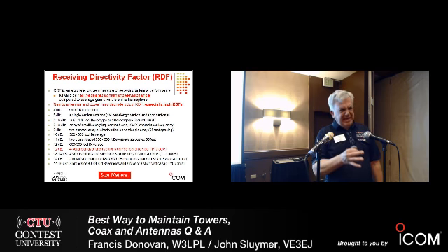Magnetic loop antennas, it's a name I don't like, but it's commonly heard by hams, or small loops, which is more accurate. Their very valuable characteristic is an extremely deep null off of both ends of the antenna. It's a vertically polarized null, and it's very, very effective in completely eliminating local noise sources, but it'll only eliminate one noise source. It'd be pretty unlikely you have two RFI sources at exactly the same azimuth. And that very deep null is only a few degrees wide, but it will eliminate that source.